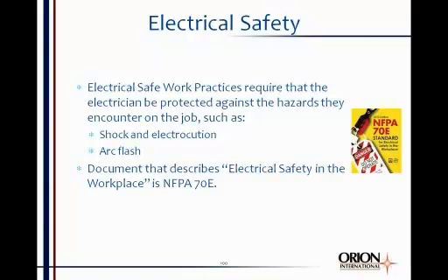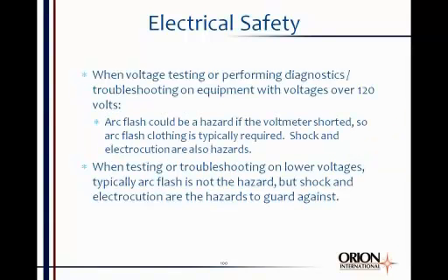The main hazards of electricity are shock and electrocution, which is defined as shock that results in death. If you die from shock, it's an electrocution. Okay? And arc flash. Arc flash is a significant hazard because of the high temperatures and blast forces involved in an arc flash event. NFPA 70E gives us some strong recommendations of how we can work in the trade for many, many years and not get hurt from shock or die from electrocution or get arc flash burned. And most responsible companies expect their electricians to follow proper electrical safety rules.